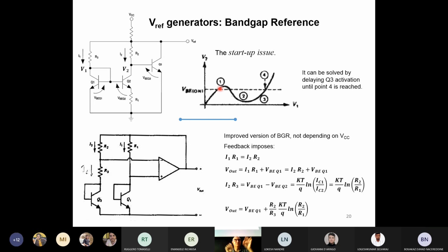You studied the parametric graph, something like a parametric expression. Also, Lisa showed a picture. I don't know if you've done that. Anyway, the voltage of V1 is going up. But here, something strange happens on V2. When the input voltage reaches the VBE on of 0.6 volts, transistor Q1 starts to conduct. Also, transistor Q2 starts to conduct.